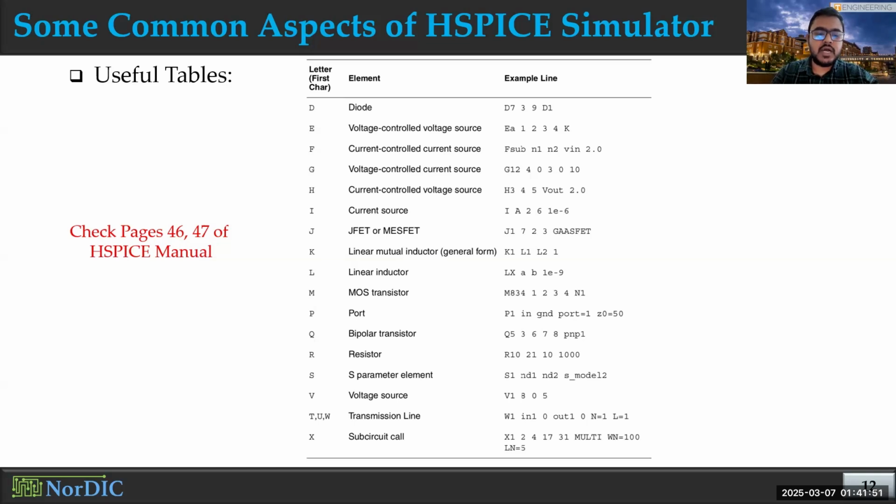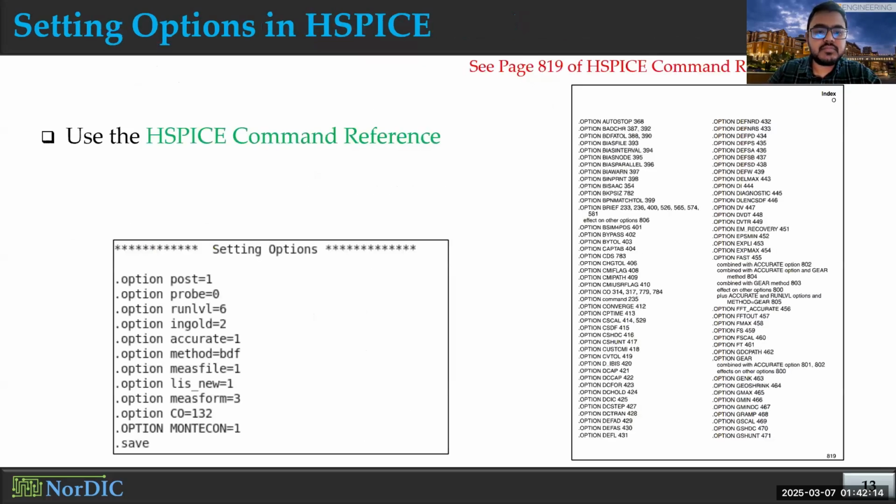So it will be able to import from its library the unit of this component and how this component works. For example, if you define a resistor with an R, it will understand the unit is ohm, and the current-voltage relationship of a resistor is already defined there. So you have to name them properly when you build the main circuit using these different components.